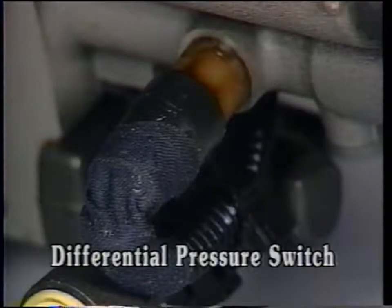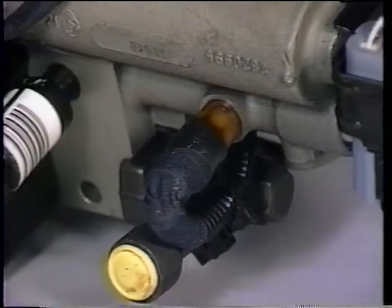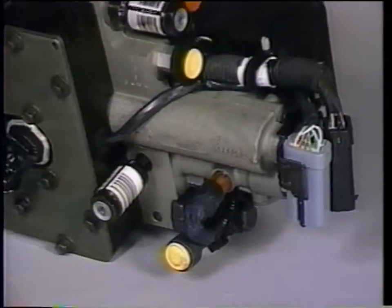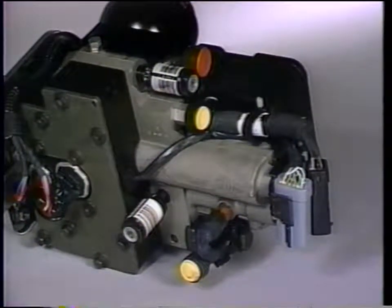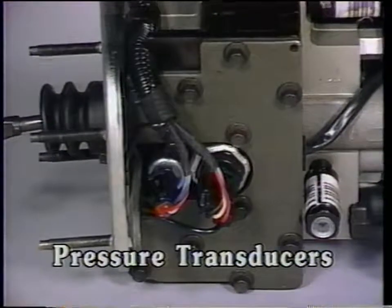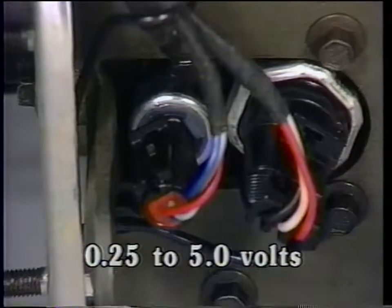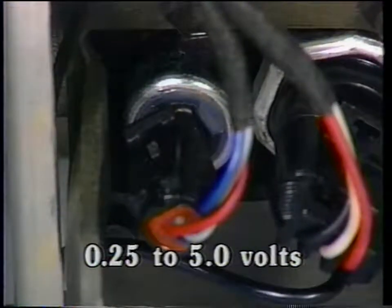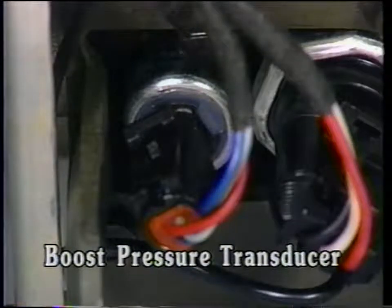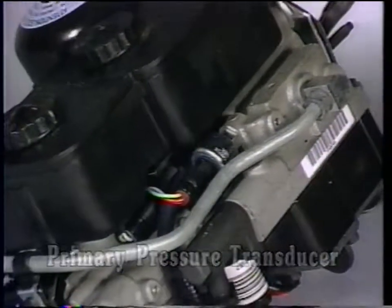There's also a differential pressure switch to detect pressure differences of more than 300 psi between the primary and secondary sides of the brake hydraulics. A problem here will illuminate both warning lights. 2 pressure transducers are also used in the Bendix 10 system on the modulator assembly to detect pressure problems. Each generates a voltage of 0.25 to 5 volts that is proportional to the amount of pressure. One monitors boost pressure and is located on the bottom of the modulator assembly. The other monitors primary pressure in the master cylinder and is located on the left side of the hydraulic assembly.